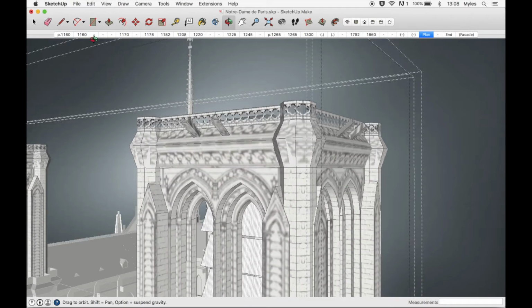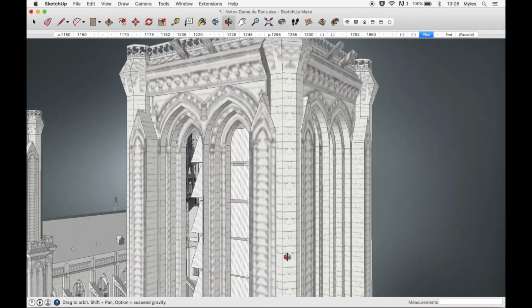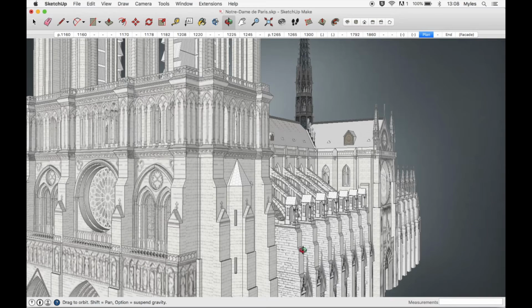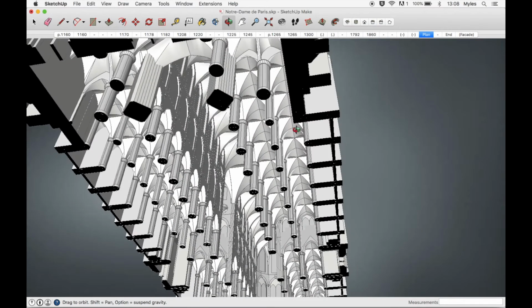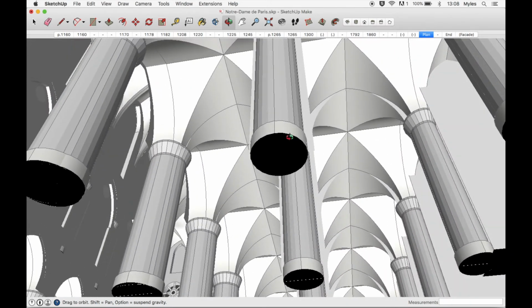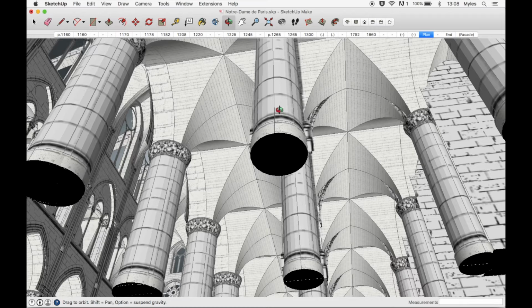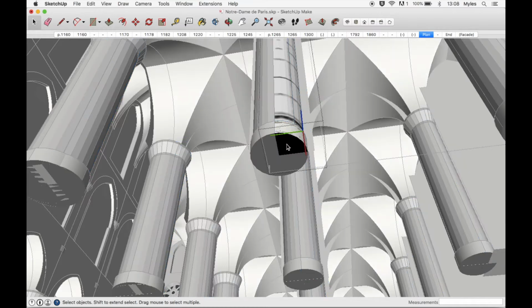And not only can this process of using rotational geometry save you time and the number of components and the number of polygons for the tower, this can also be used for all manner of other parts of the building. So for instance, these columns have rotational geometry. So when I zoom in, you'll see that I didn't create the entire column, I only created 1/4 of the column. And I've rotated it.